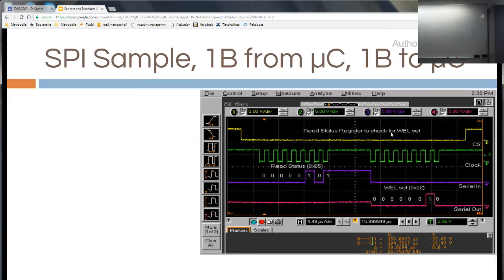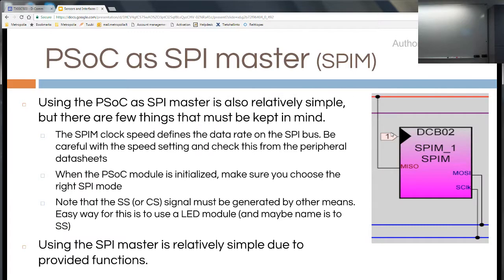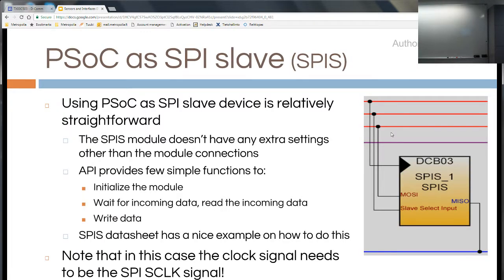When you have transferred a byte, these devices are all 8-bit, meaning that when you are shifting the data from that 8-bit register of this block to MISO or MOSI, you are also reading the read line into the same register. So it shifts bits out and gets bits in at the same time. It means that after you have made the one byte transfer, you need to go and read whatever was in that register. Otherwise you will lose it.